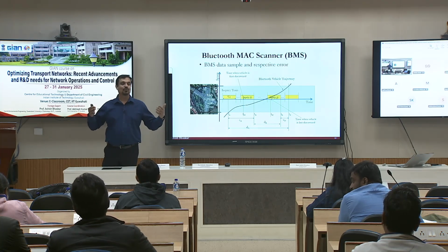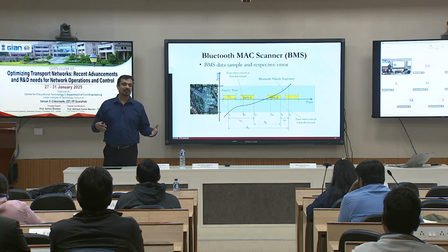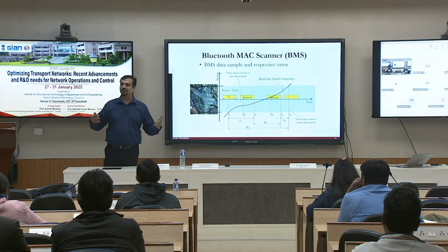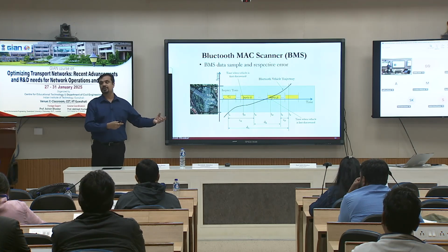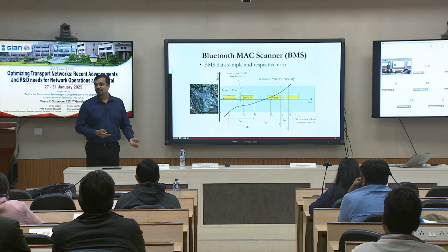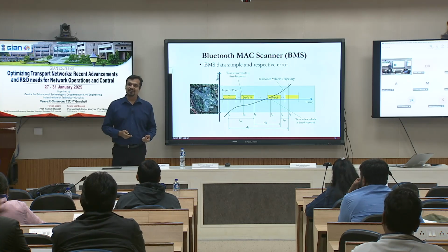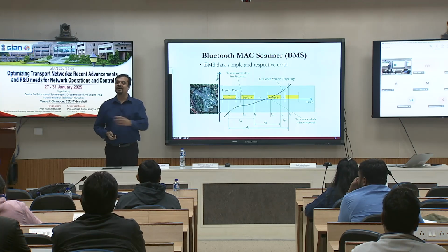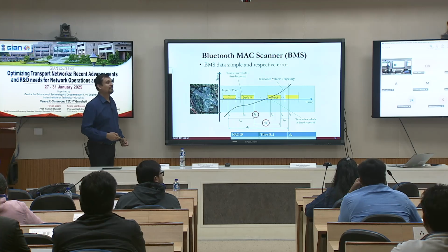It depends. You have to know what road characteristic you're talking about. If I look at the Bluetooth travel time in the Brisbane CBD area where I have a lot of pedestrian activity happening, it's very hard. But if I'm looking at an area where I know there's a high amount of car composition, there I will have more confidence. So the confidence of this data set depends on the characteristics of where you are focusing. Different sections will have a different confidence. There is no one single confidence for the data for the entire network, which I will present in the coming slides also.